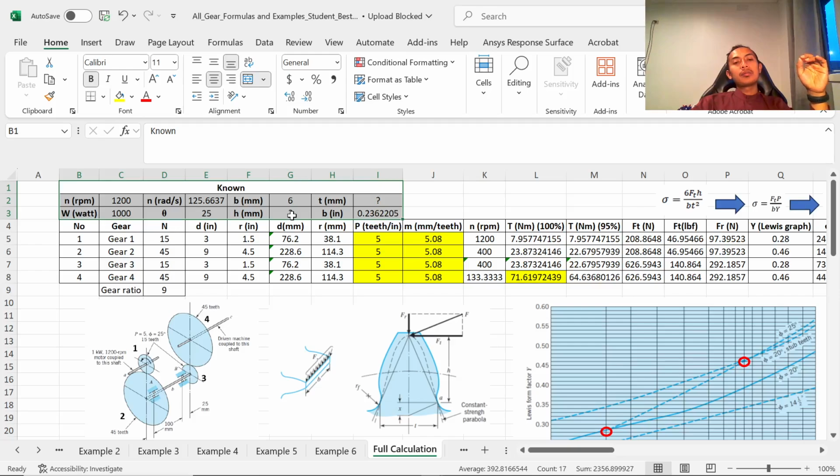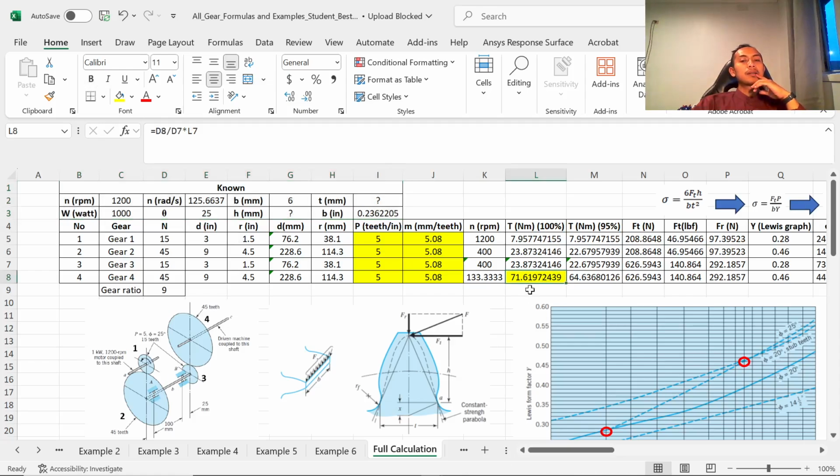If we want a high torque, say we need 70 newton meters, and we come out with 71, that is enough. This is the initial torque, and we want to convert it to 71, which is 9 times, and the speed is reduced 9 times.